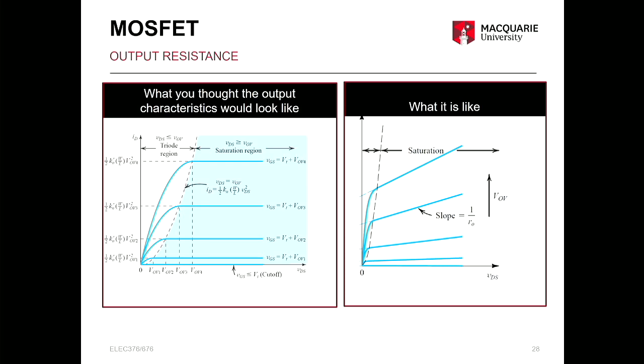So at pinch off, we saw the channel is getting to a point that there is no thickness to that channel, or channel thickness is 0. But still there is a current flowing because you have an applied voltage up to a point that the channel is pinching off. When you increase the voltage further, the channel recedes backwards, but the voltage is still increasing, so there is still a current flowing through tunneling. So we will see that here in the channel length modulation.